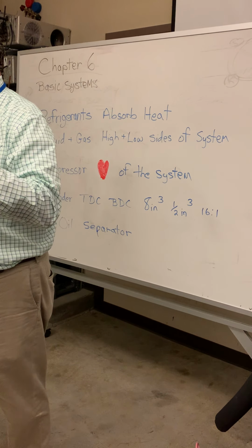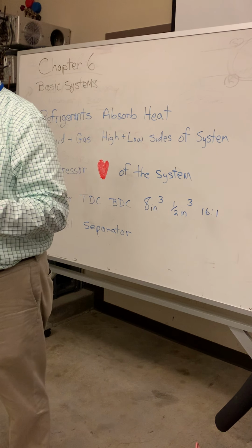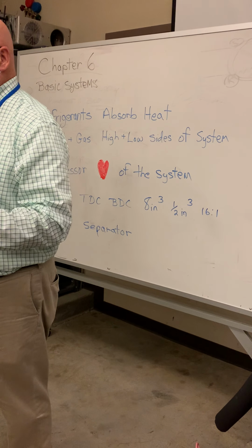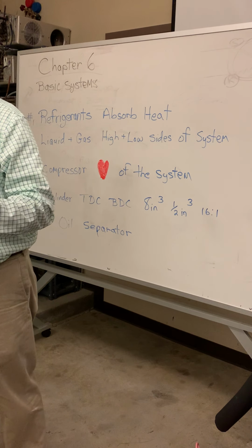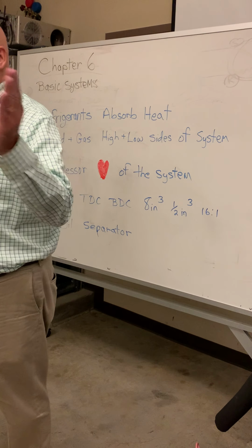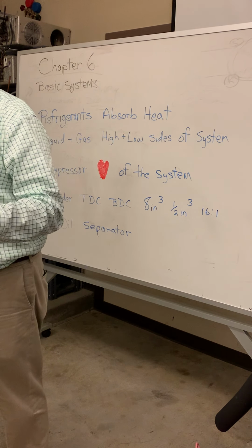And they're flat pieces of metal. If any of you have a 2-stroke engine at home, maybe a dirt bike or something like that, that has the same exact valve. And so when the liquid gets there, it's going to bend the valves. That's what's going to happen. That's called slugging. That ruins your compressor.